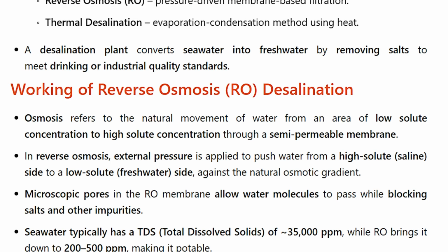Working of reverse osmosis, RO, desalination. Osmosis refers to the natural movement of water from an area of low solute concentration to high solute concentration through a semi-permeable membrane. In reverse osmosis, external pressure is applied to push water from a high solute, saline, side to a low solute, freshwater, side, against the natural osmotic gradient.